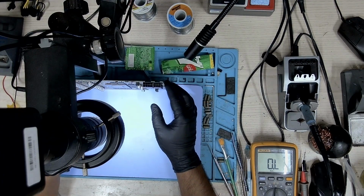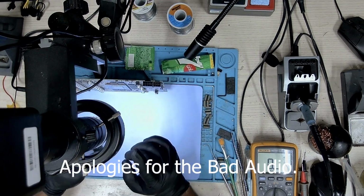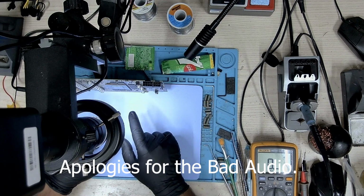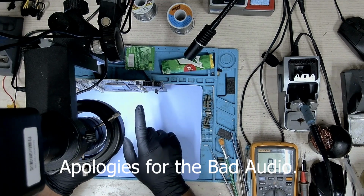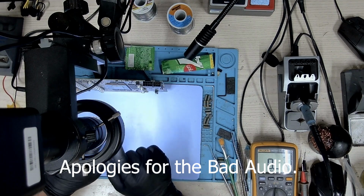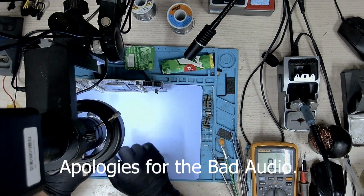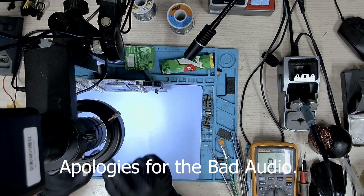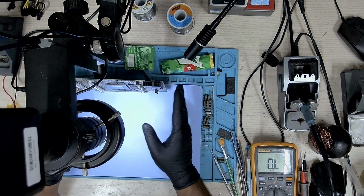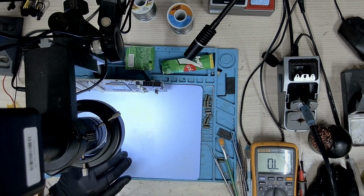So the memory has been installed. I'll just wait for the card to cool down, then I'll do a resistance check. After I do the resistance check, I'll go ahead and change the straps for Samsung memory. So current straps are set for Hynix. I will have to change that to Samsung, and I will show you how I do that. I'll just pause the video and start again once the card cools down.